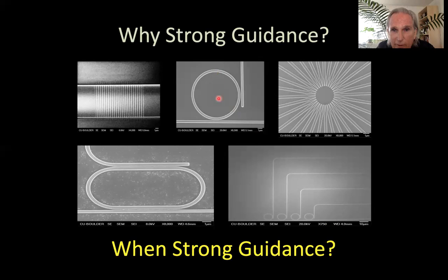This is a 5 micron radius ring. This here is an add drop multiplexer. Over here, if you're at the right wavelength, it couples out. If you aren't, it goes through. So it's, I guess you could say, a pass filter or whatever. If you put a heater around the silicon, or if you make it a PN junction, you make this a very high bandwidth modulator and a very small modulator. It's 5 microns or 10 microns all the way across.